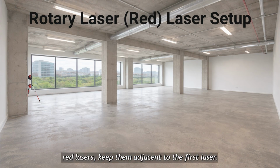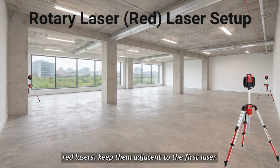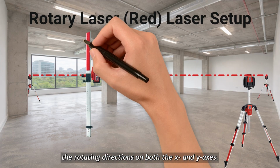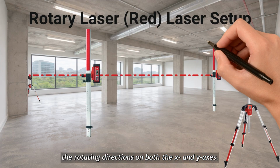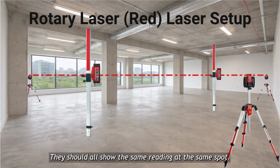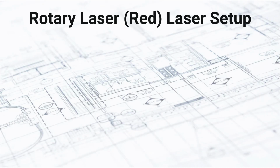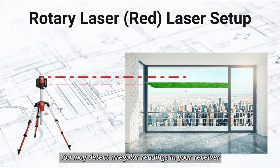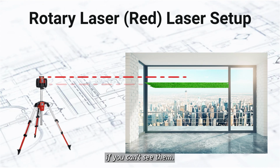If you add additional red lasers, keep them adjacent to the first laser, place them near corners away from windows, and then match the rotating directions on both the X and Y axis. They should all show the same reading at the same spot. If you see faint or duplicate lines, block reflections before you continue. You may detect irregular readings in your receiver if you can't see them.